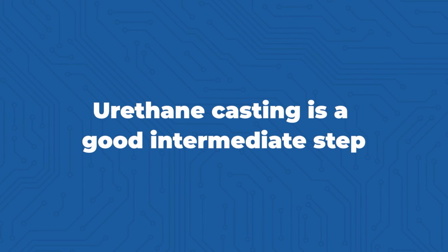That can be a really good option to transition from prototype, but you need some high quality samples to show customers, but you don't yet want to spend thousands on injection molding. Then urethane casting is a good intermediate step.